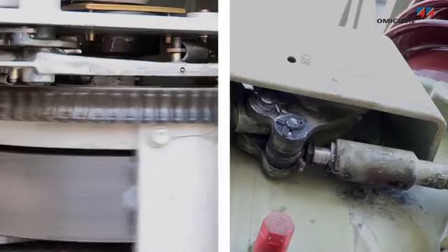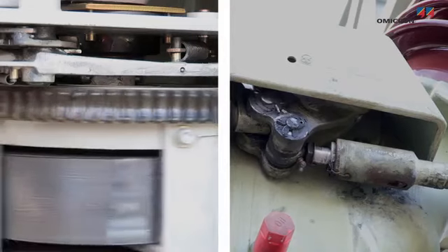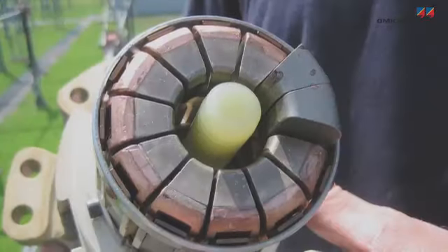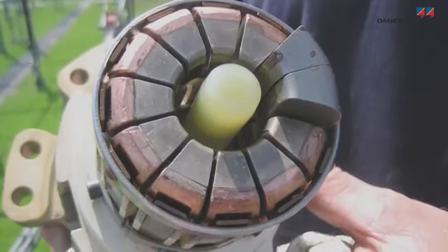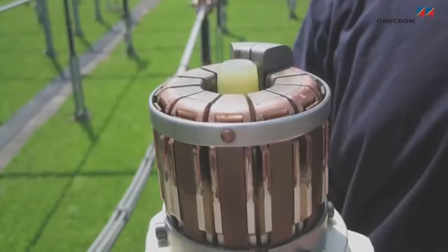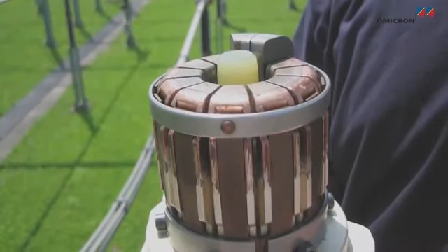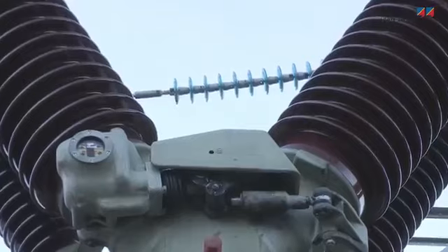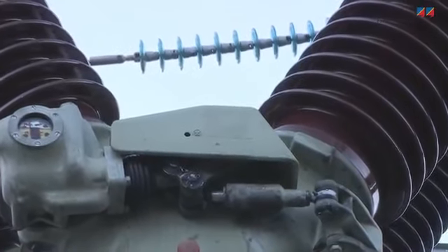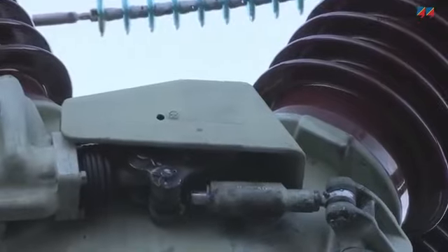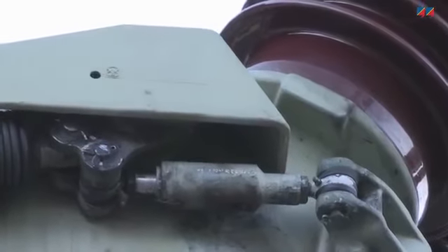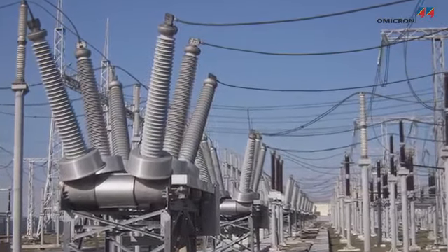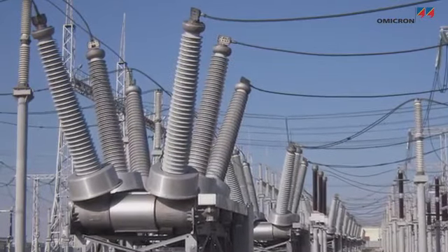The interrupter and the mechanical drive are the main components that are subject to wear and aging. The thermal stress of load currents may cause corrosion and oxidation, and the interruption of short circuit currents erodes the contact system. Environmental stresses, such as temperature, humidity, or contamination, affect the bearing and linkage surfaces of the drive. Ancillary components, such as bushings, are also subject to electrical stress aging.